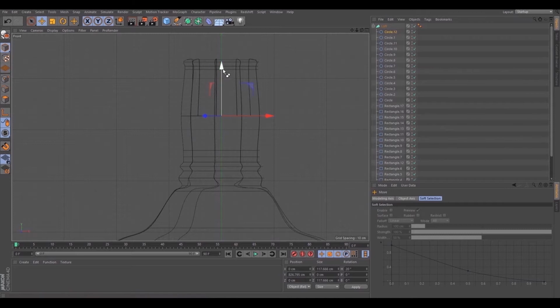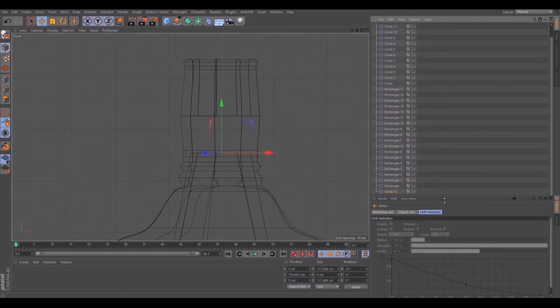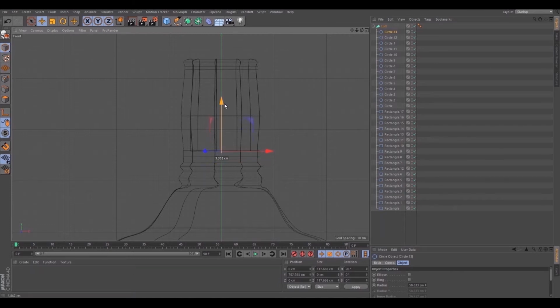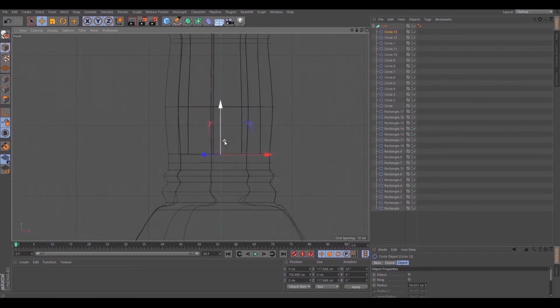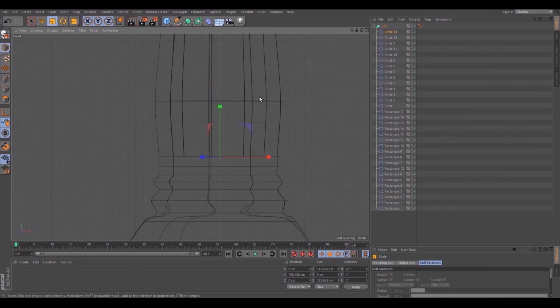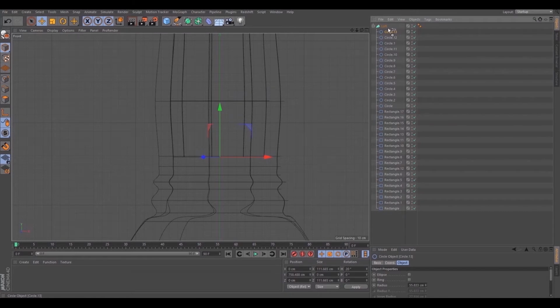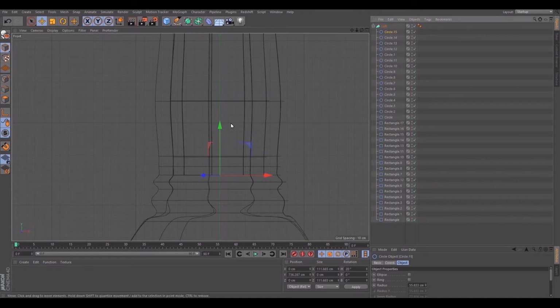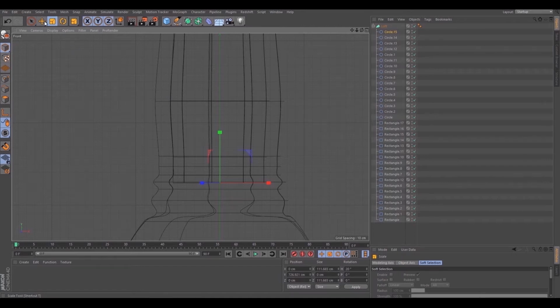If you copy an object with drag and Ctrl in viewport, it is automatically placed in the bottom of the hierarchy, but we need it on the top. 3 ways to fix that. Just move it up, or make outer and inner shape before placing it in loft, or just copy it here. Copy, move, scale and repeat. Just don't forget to change shapes from circle to rectangle where needed and adjust rounding.